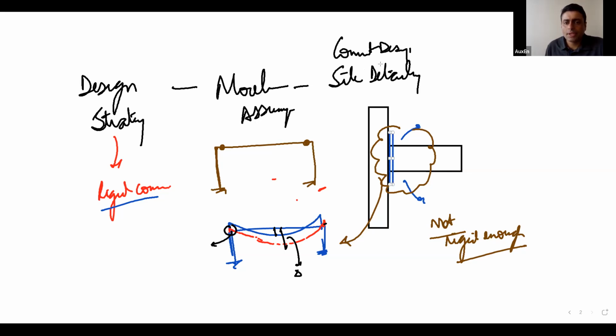You made a proper looking rigid connection, but in your model, you ended up providing releases. So again, it was out of sync.